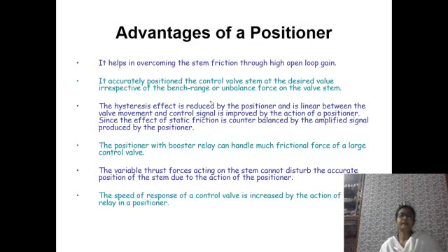The advantage is that it helps in overcoming the stem friction through high open loop gain, because it gradually changes the movement in the upward and downward direction, so high open loop gain can be overcome. It accurately positions the control valve stem at the desired position, irrespective of the bench range or the unbalanced force of the valve stem.